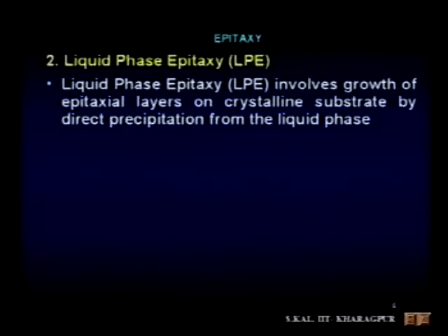The reason for using LPE is that in some cases, for some of the semiconductor films, the precursors in gaseous form are not available. And even if available, the handling of those precursors is not very simple and easy. So in those cases, liquid precursors, liquid sources are used, and handling is also easy, not difficult, and LPE is popular in those cases.